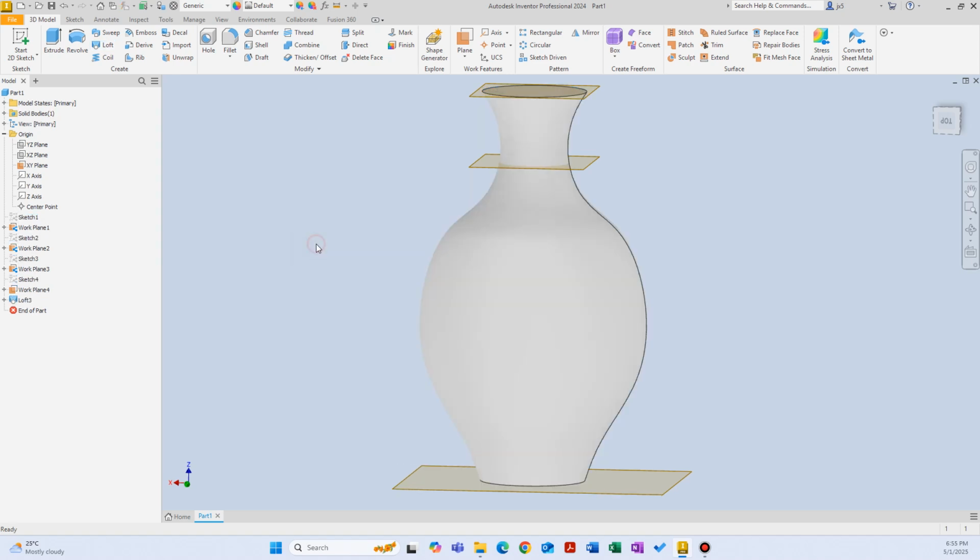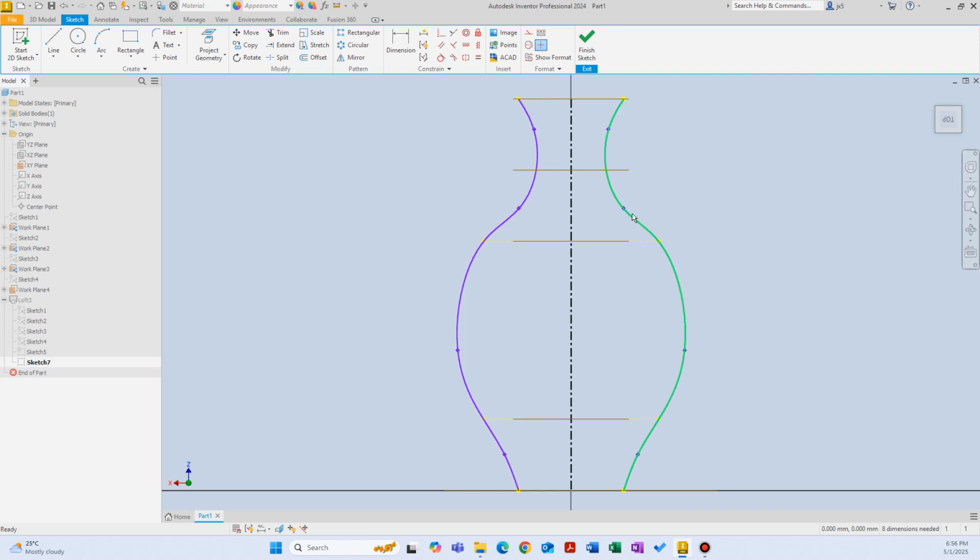Now the 3D object is created using not only the sketches and work planes and also the conditions and the loft feature, but also the rails around that we created around the sketches we used for the loft. This way it gives you more control on the design you're creating. Now you can go back to the loft feature, for example, expand the loft feature and see all the sketches that are consumed. The sketch 7 now is the sketch we used for the rails. So let's double click on that and modify it a little bit.